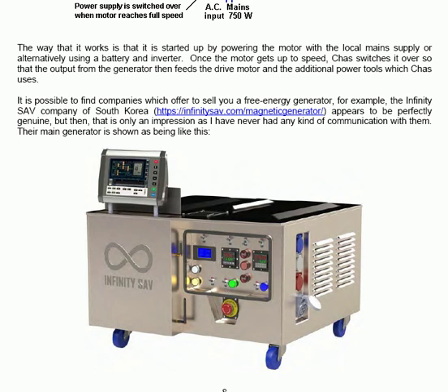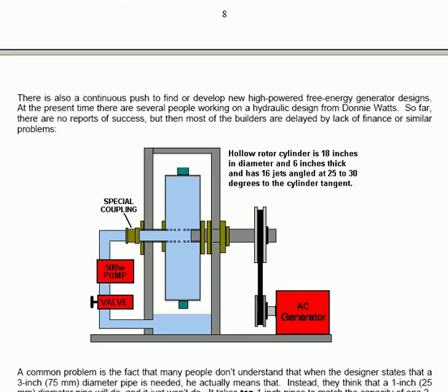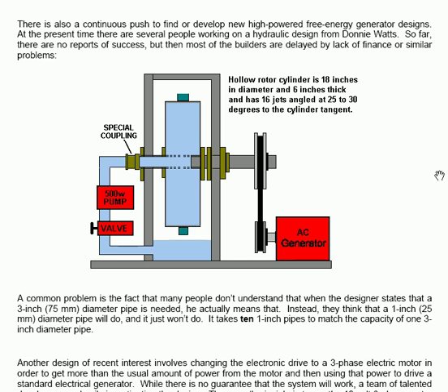There's a sump which contains a liquid, could be water. More generally, it's considered to use transmission fuel. A valve is opened and a 500 watt pump operates on a 3-inch diameter pipe, driving water into a drum which is set on bearings. The drum's got jets top and bottom, and that causes the drum to rotate inside the housing itself. The rotating drum then turns a pulley link to an AC generator, which gives you the power to drive equipment.